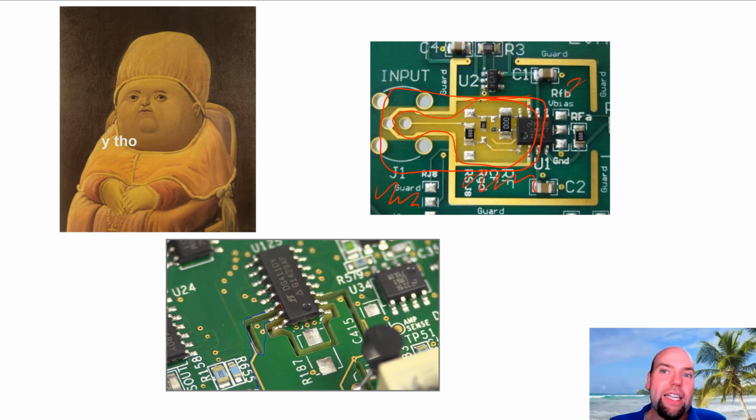The solder mask has some resistance that is lower than fiberglass. So all the circuits are built on the fiberglass part of the board with no solder mask, because the solder mask had too low of a resistance. It was basically in parallel with what should be big resistors, and so it creates an issue.